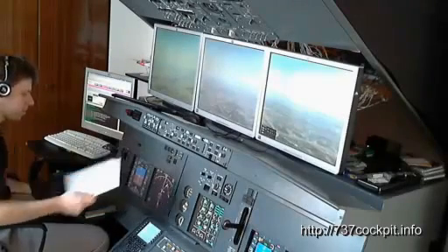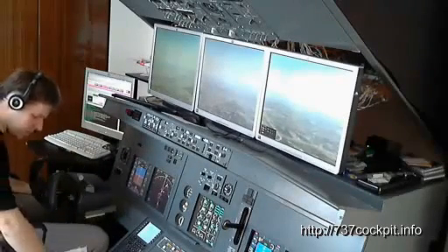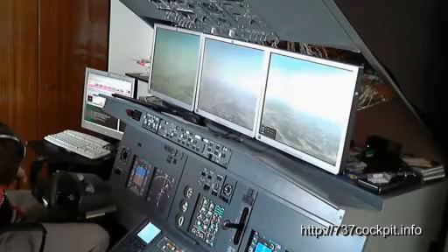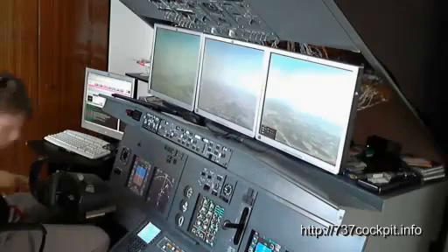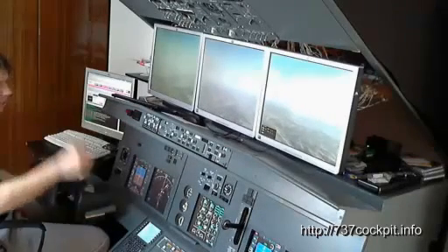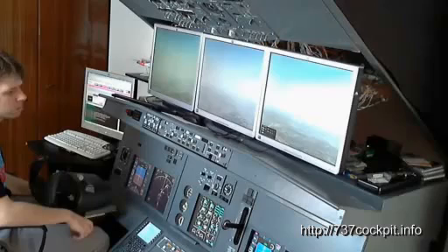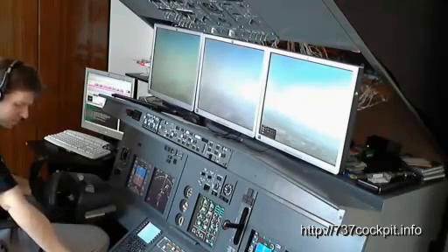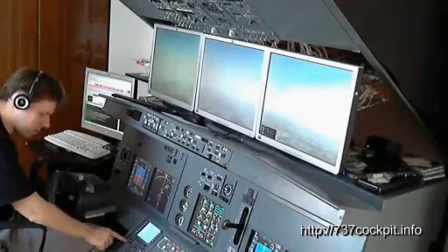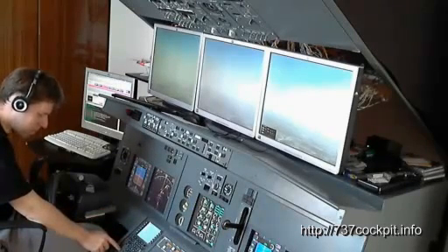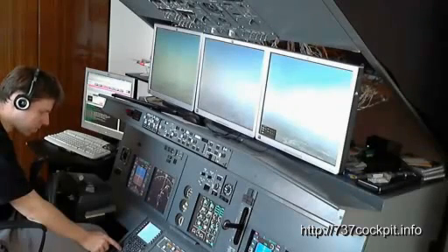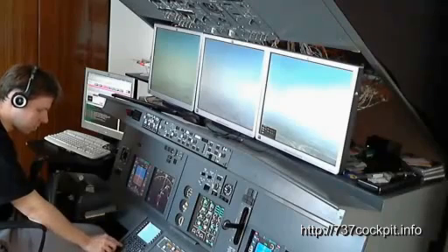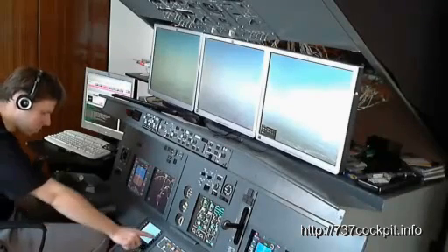So the ADF we have reprogrammed to Sierra Tango Echo Steinhof. And after passing Sierra Tango Echo, we will change it to Whiskey Oscar. Whiskey Oscar will then, in case of any missed approach, be our breakout point to the right, direct to Sollenau. That means we will enter the Sollenau frequency 115.5 from our NAV 1. We had it before on the NAV 1, now to NAV 2.